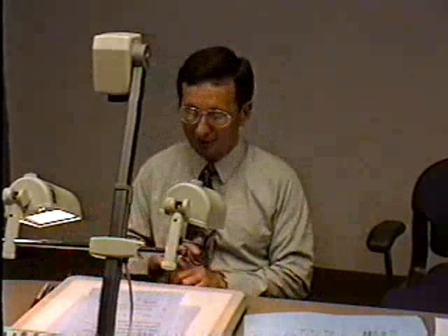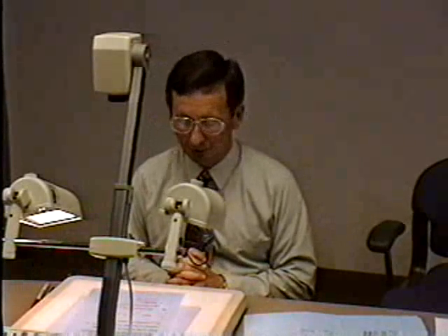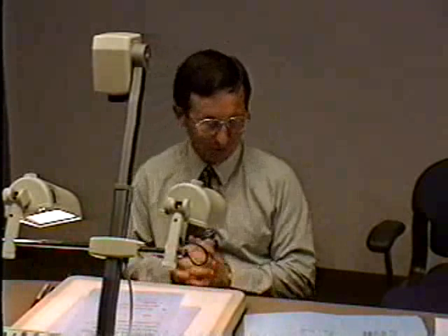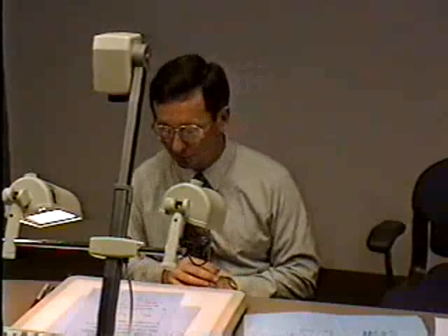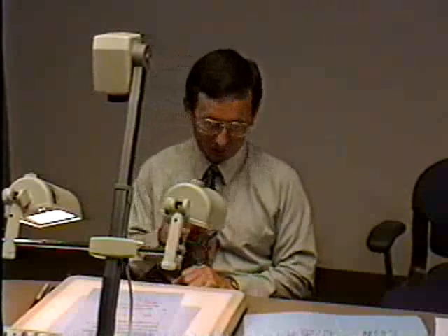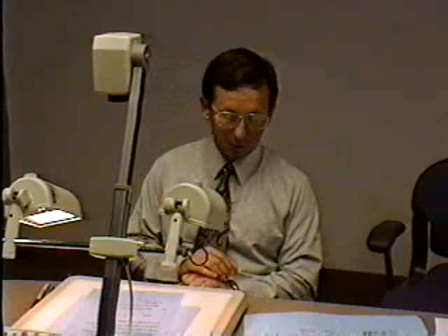And as someone just pointed out, that is the buoyant force. So what's the 44.8? That's the force in the rope minus the weight of the wood. Yeah, you're right on target. The 44.8 is the force in the rope, and the 124.8 is the buoyant force. All we've done here is compute the buoyant force.